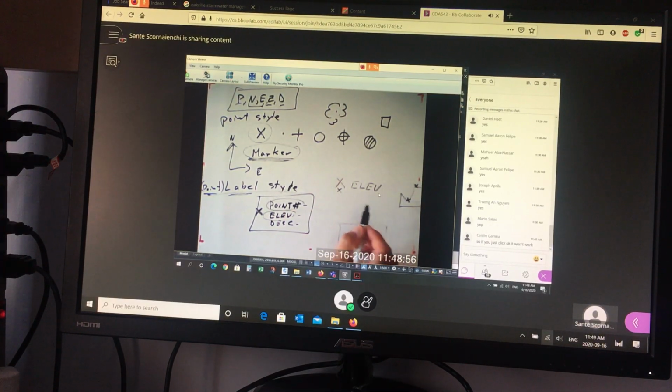So what I've done in the past is I don't put that point in. Here, I actually show the elevation of the pavement, and then I have another elevation of that design point, and I add 15 centimeters to it. So then it can show 2 numbers. One is always 15 centimeters above the other. You can actually program that into the style.